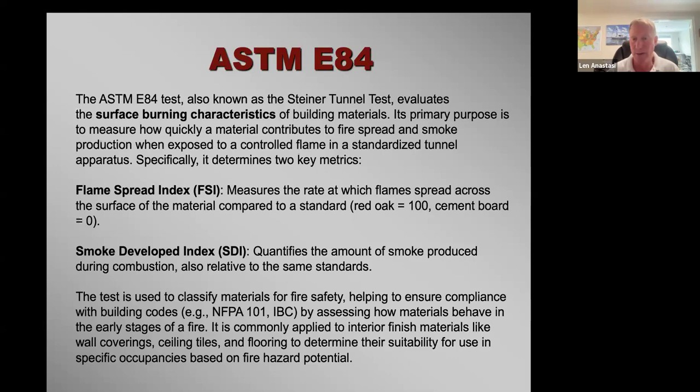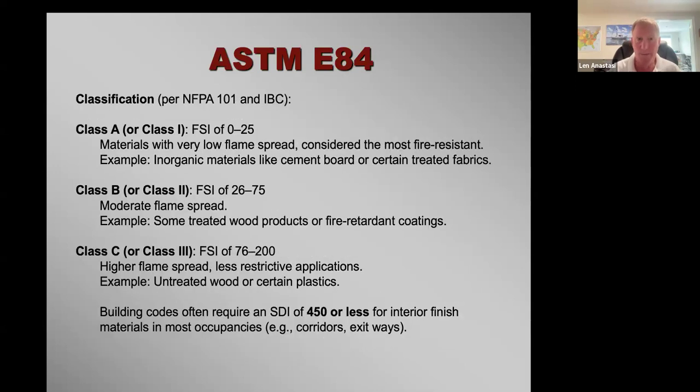And that's the comparison that each of these products are measured to. So a Class A rated under ASTM E84 is a flame spread index of 0 to 25. Class B is 26 to 75. Class C is 76 to 200.